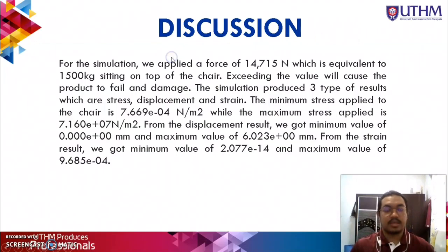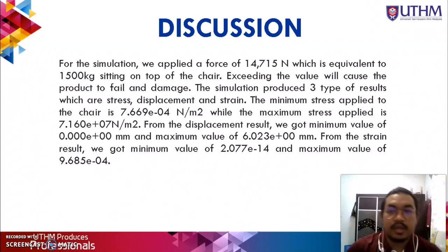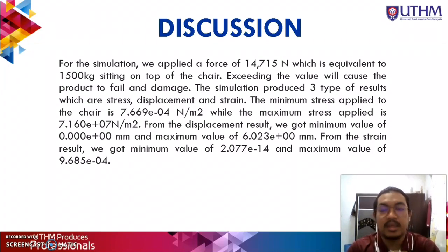Next is the discussion. For the simulation, we apply a force of 14.715 kilonewton, which is equivalent to a 1,500 kilogram object sitting on top of the seat, and exceeding this value will cause the product to fail and be damaged.